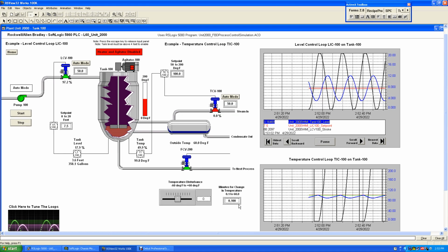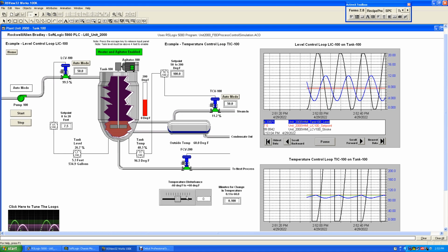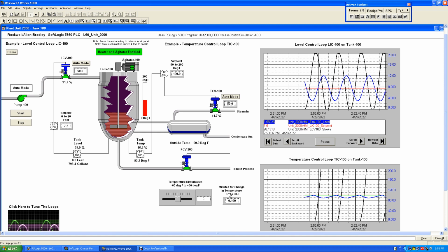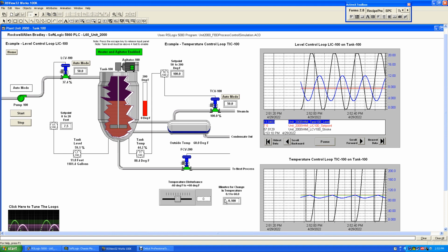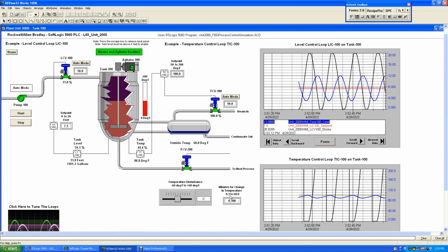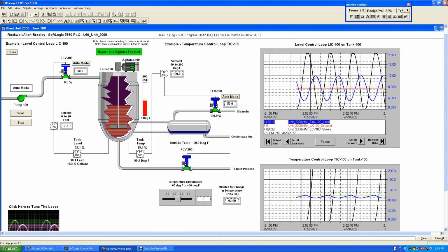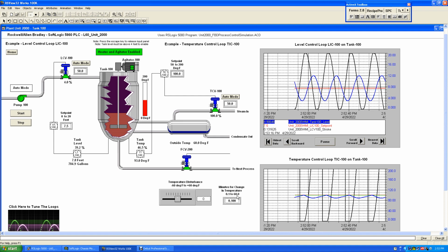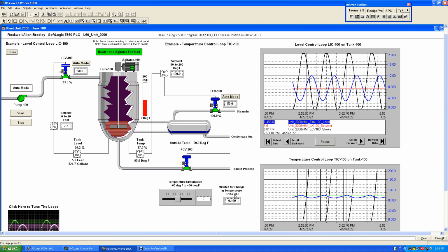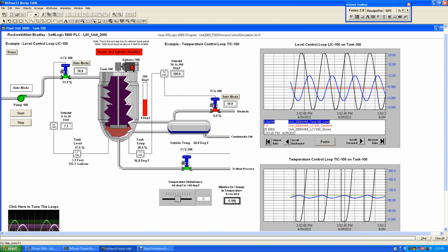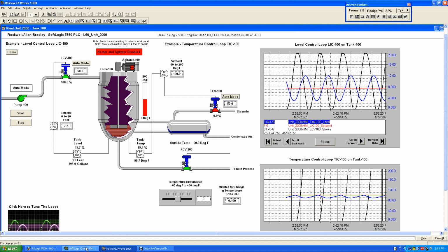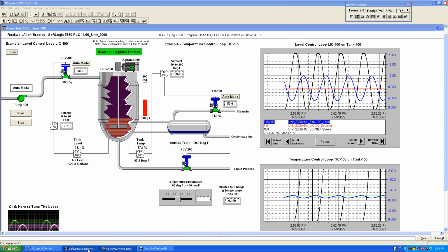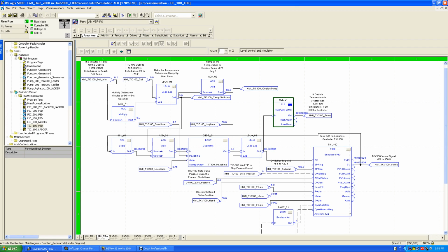So this gives you plus minus 60, and it doesn't just give you a temperature, but it ramps up that temperature over time. We take this time right here in minutes to change the temperature from 0.1 to 60 minutes. This is minutes. So in the HMI, it's in minutes, but in the PLC, it'll be seconds.